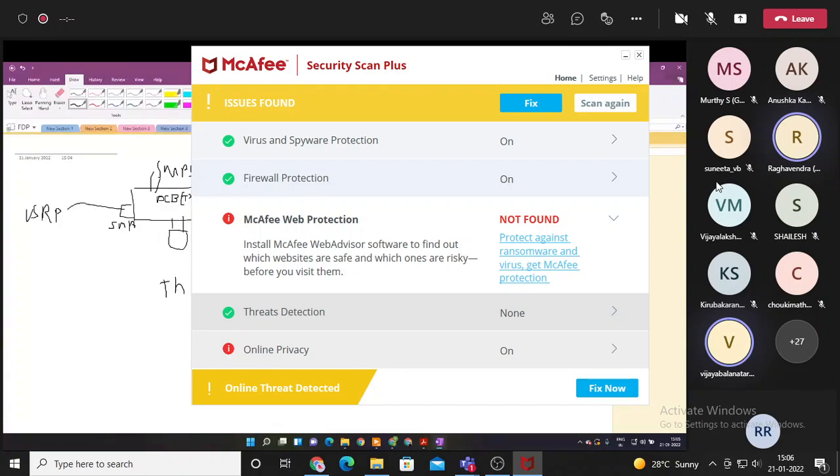The receiver circuit is also actually pretty simple. There is a photodiode over here that receives whatever light is impinging on it. Again, this photodiode has a thresholder on it. It receives the light signal and thresholds it. By the way, this is also connected to the SMPS because it needs power. It is converted to the proper electronic signal format, analog signal format, and then it is sent back to the USRP receiver.